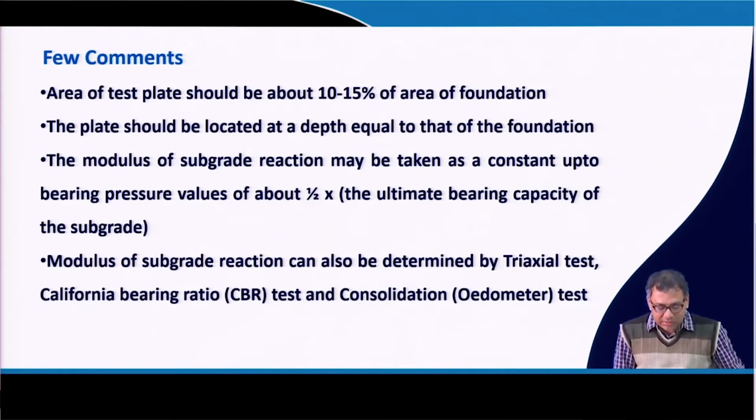Now, a few comments: when you do the plate load test, your plate size should be taken such that at least 10 to 15% of the foundation area is covered by the plate size. Okay. Then plates should be located at a depth equal to the foundation. If not, then you have to apply the foundation depth corrections, and sometimes the depth correction is given for a surface plate. That means the plate load test is done on the surface. Okay, but sometimes it may be done at a certain depth, but that is less than the depth of the foundation.